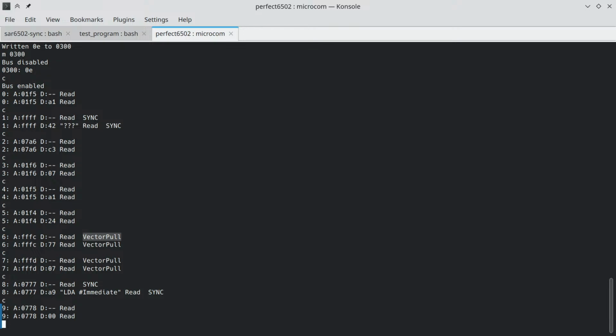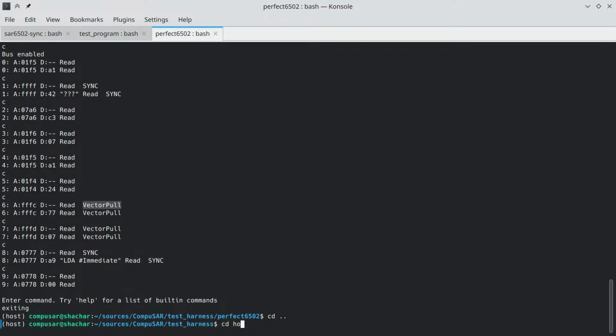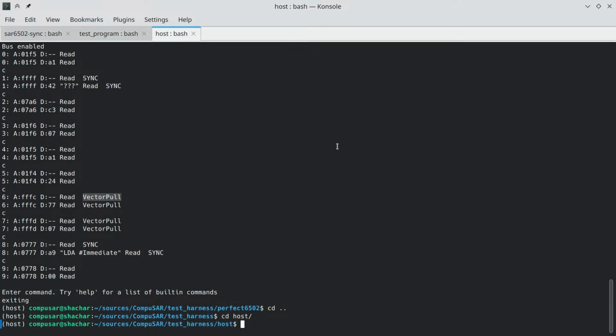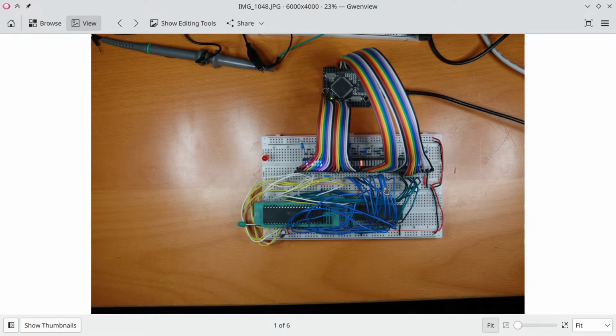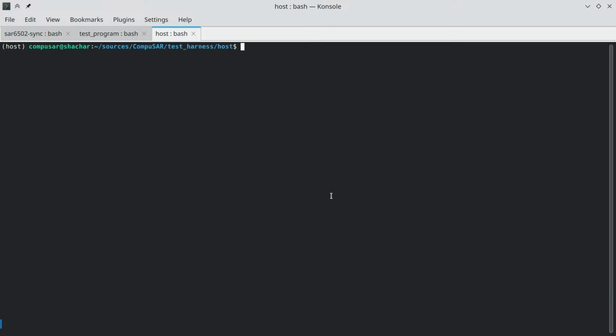So what I can do is take the test program I converted into a mem file of a memory image and write a Python program that will read that and dump it through the serial interface to the memory of the actual test setup, and then execute this program and record what it's doing. Now, it takes a while. I will actually show you how long it takes.